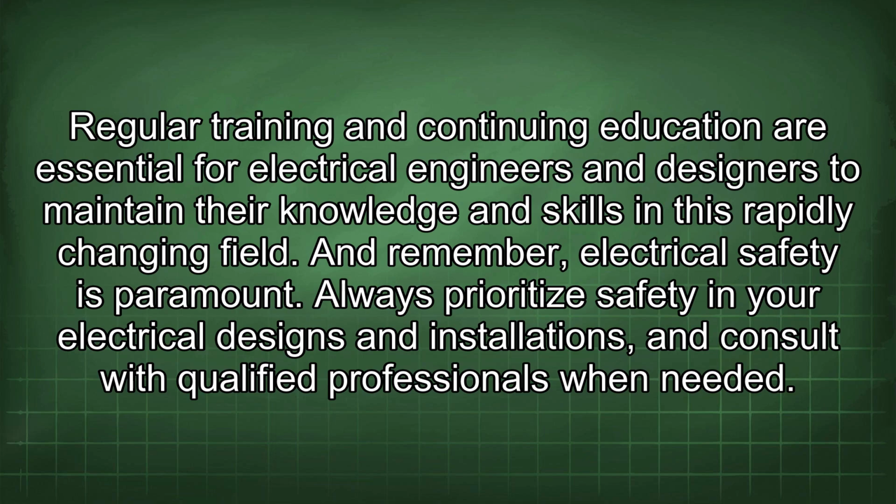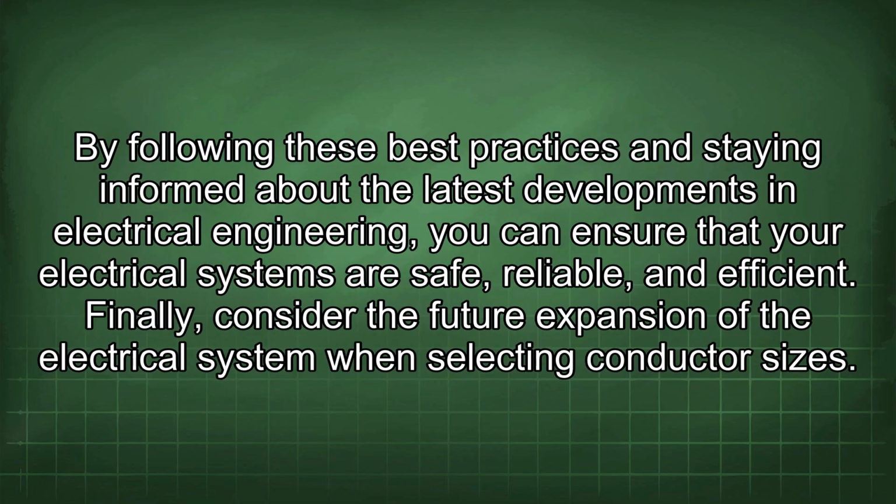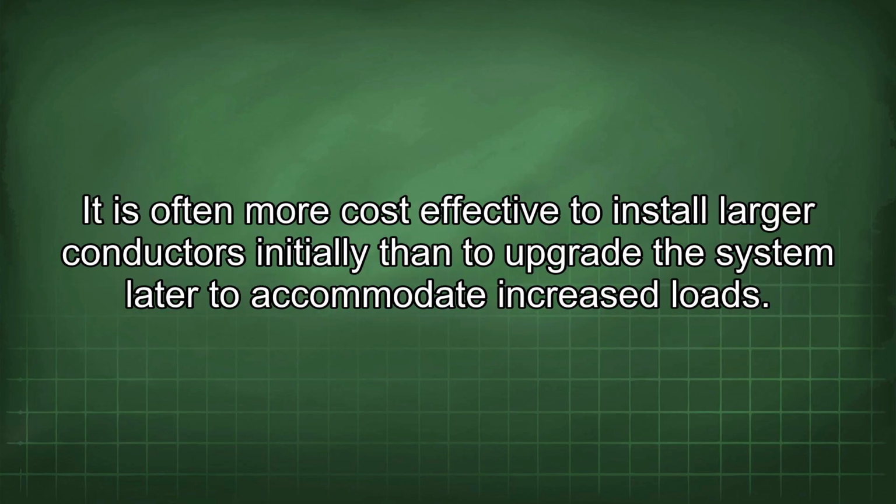Always prioritize safety in your electrical designs and installations, and consult with qualified professionals when needed. By following these best practices and staying informed about the latest developments in electrical engineering, you can ensure that your electrical systems are safe, reliable, and efficient. Finally, consider the future expansion of the electrical system when selecting conductor sizes. It is often more cost-effective to install larger conductors initially than to upgrade the system later to accommodate increased loads.